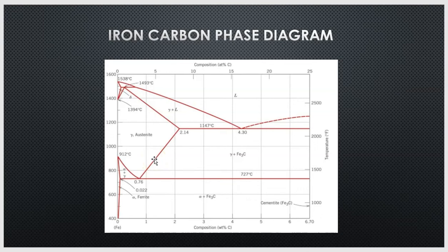This would bring it back from a martensite grain structure to something around ferrite or even pearlite, somewhere around there. Then if you wanted to normalize it, you can bring it up to a certain temperature and go through the various heat treatment processes. So this chart really comes in handy for people who are heat treating metal.